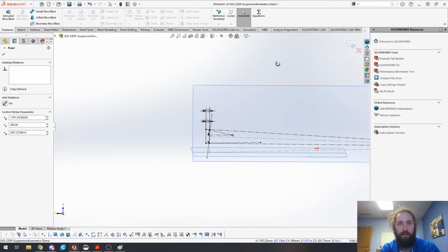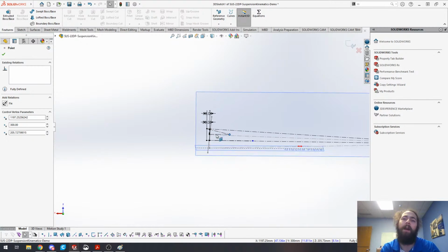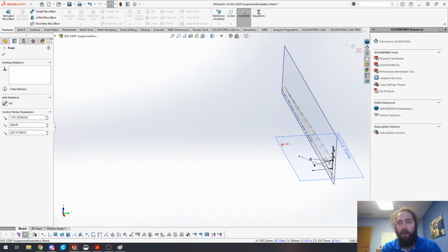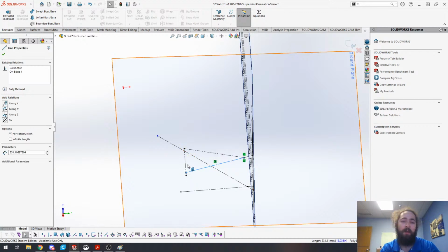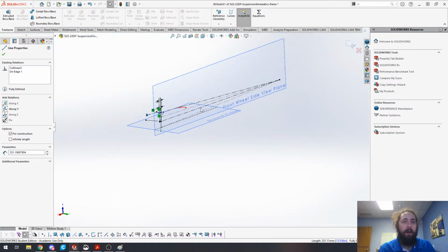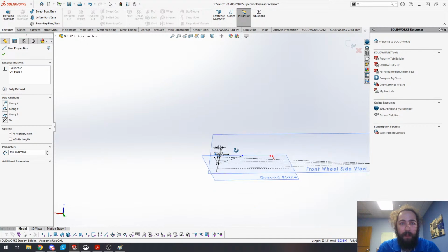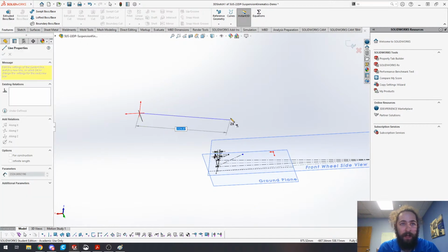So what that did is make sure that this is aligned along the X axis, or I guess it's kind of flat. I don't know how to really explain that. Basically, what we did here is make it so that the rear point of this axis will lie on a plane. Remember when we defined this front view swing arm, we said control arm points can't lie anywhere within 600 millimeters because we've got driver legs there. So we're making sure that this axis is on a plane that's 300 millimeters from the center line, so 600 millimeters between these two axes. Hopefully that makes sense.